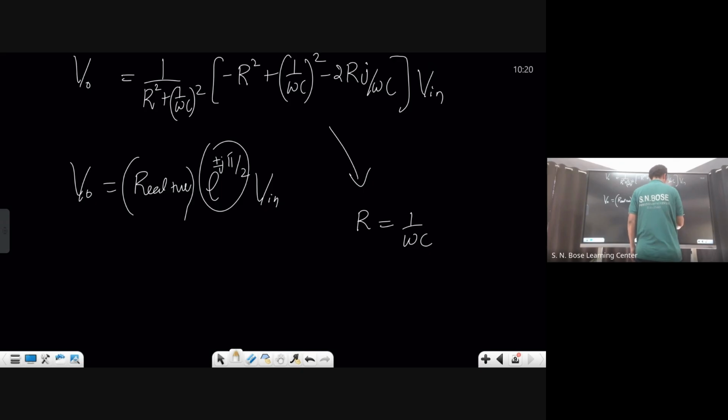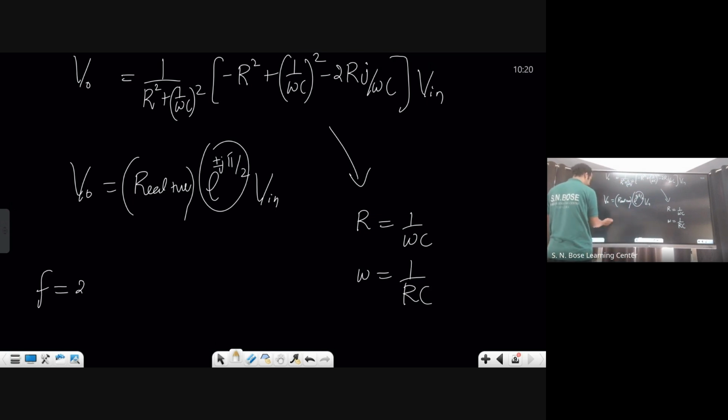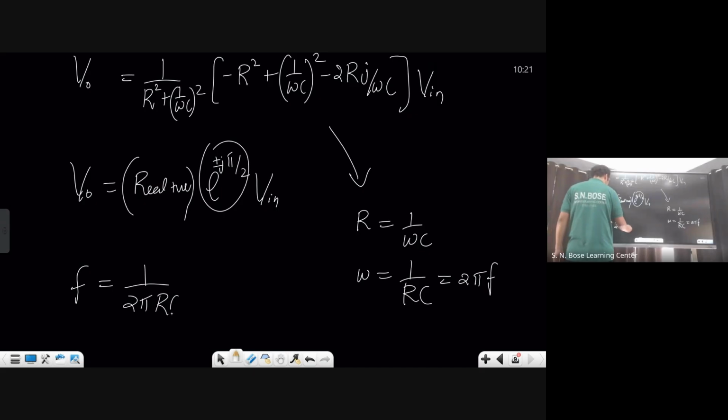What did he ask? He asked for the frequency, 1 by RC. Can you quickly do it? Omega is equal to 2 pi into F. So F is 1 by 2 pi RC.